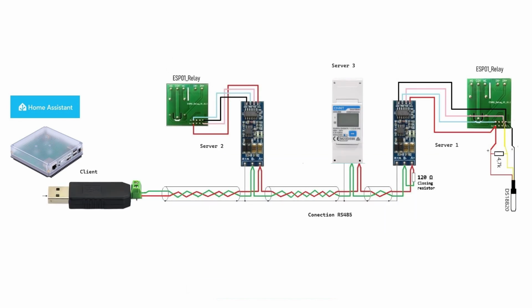RTU, which is physically with RS485 wiring, a single crossed pair with mesh. The connection does not allow star sections, but the different devices must be connected one after the other and the last one must have a 120 ohms resistor connected in parallel. It only allows 32 devices per loop, but we can create several loops.